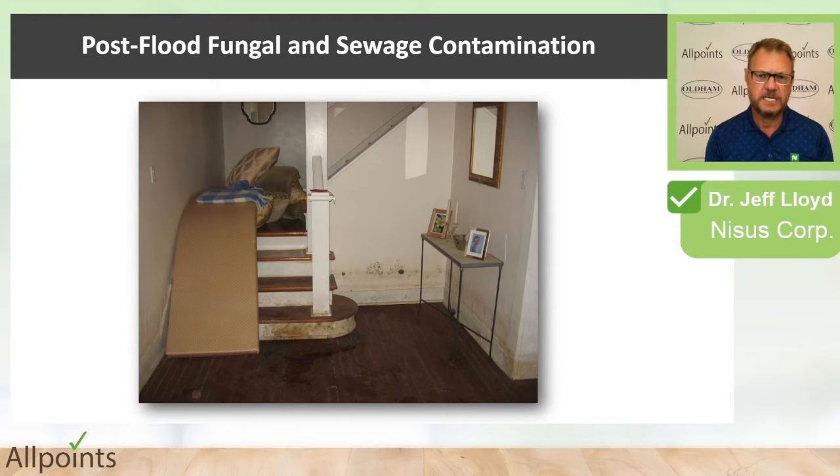Okay, this particular picture was probably taken about 2 weeks after the floodwaters receded, by the level of fungi I can see growing, but the level of fungal growth depends on temperature as well. So if this was in a cold time of year, in a cold environment, the fungal growth would be much slower than if it was a really very, very warm, hot climate, then it would be much faster. So you don't have long. The faster you can act to dry the structure, the better the homeowner will be.